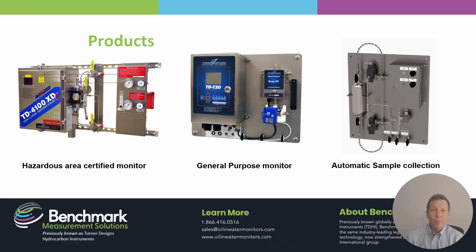When an operator wants to know the type of hydrocarbons that are in the water, a SampleTHIEF can be used in conjunction with these two monitors. This will automatically collect a water sample when an oil alarm is actuated. Operators can collect the water sample, take it to a laboratory where it can be analyzed for the type of hydrocarbon to help identify the leak source.